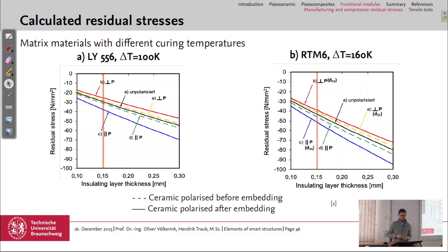We needed to have the ceramic pre-stressed in compression, and if we have a residual stress really in compression, then we can apply more tensile stress until failure.